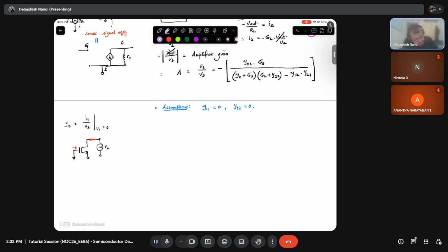Your capacitor plates are this and this. So your signal is not directly applied to the capacitor plate, right? So the AC current, that is your I equals C dV/dt, will be very small. That is why this component can be ignored to 0. Okay, so this is a justified approximation. Fine.